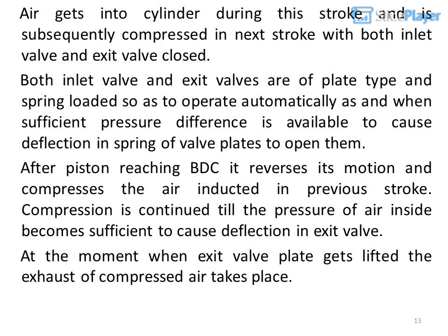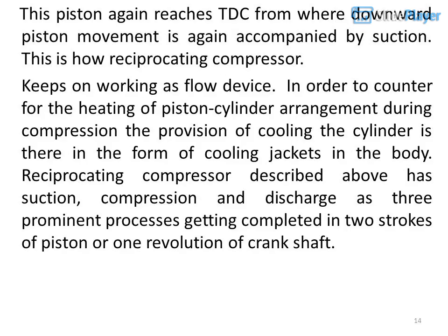After the piston reaches BDC, it reverses its motion and compresses the air inducted in the previous stroke. Compression is continued till the pressure of air inside becomes sufficient to cause deflection in the exit valve. At the moment the exit valve plate gets lifted, the exhaust of compressed air takes place. The piston again reaches TDC, from where downward piston movement is again accompanied by suction. This is how a reciprocating compressor keeps on working as a flow device.